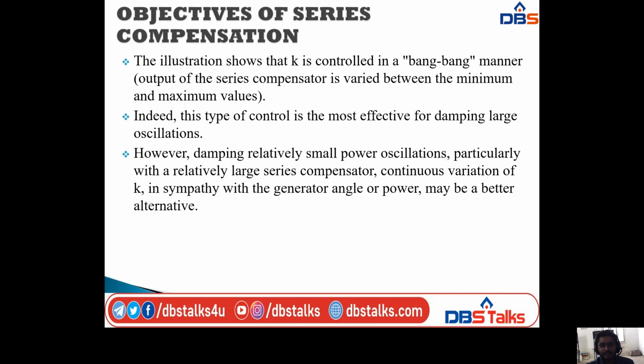However, for damping relatively small power oscillations, particularly with a relatively large series capacitor compensator, continuous variation of K in sympathy with the generator angle or power may be a better alternative. So that is the explanation for the power oscillation damping.